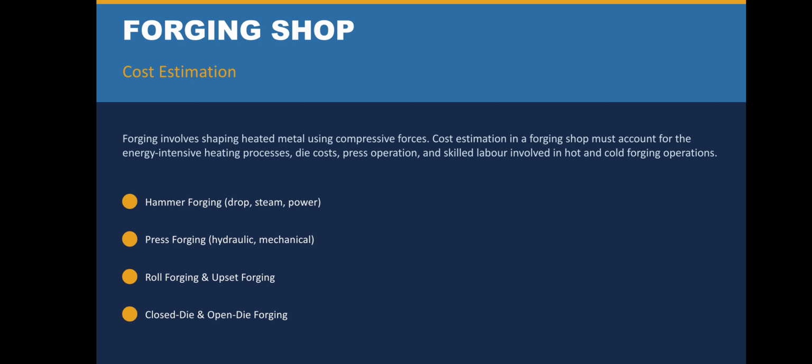Cold forging means when the forging is performed on the metal below the recrystallization temperature, it is called cold forging. Examples include components like bolt heads, nails, rivets, etc. are produced by cold forging.